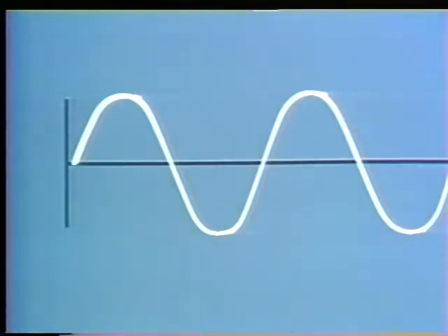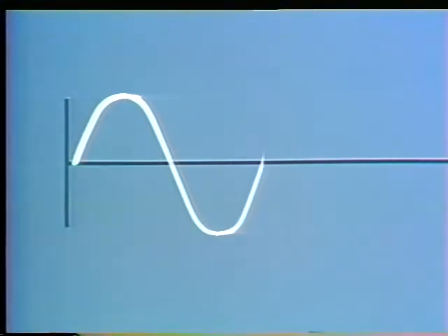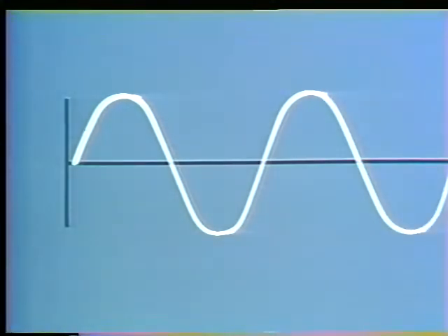The sine curve for a single-phase alternating current is fairly simple to understand. The curve represents the intensity of the current flow. Starting when the current is 0, it increases to its maximum, then decreases. The direction of the current changes, and the current again increases to maximum and then decreases. Each repetition is called one cycle, and there are usually 60 cycles of alternating current in every second. Now, that's how AC current changes.